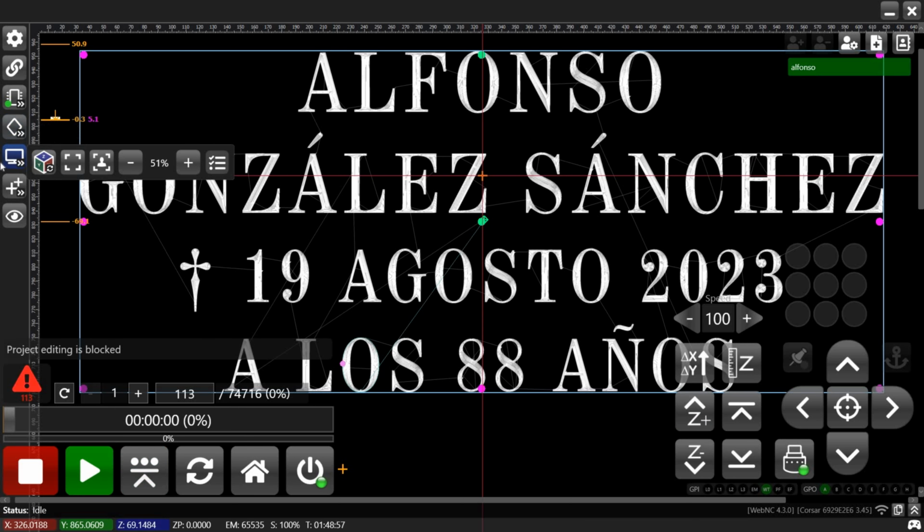Here we have a 5.1 mm slope. With a maximum cutting depth of 0.3 mm, it is obvious that with such a slope this text cannot be engraved, as the inclination is more than 10 times greater than the maximum depth. In addition to this, when performing a lettering job, we should use continuous scanning. It is because after polishing, the surface of the stone will always have some uneven areas.